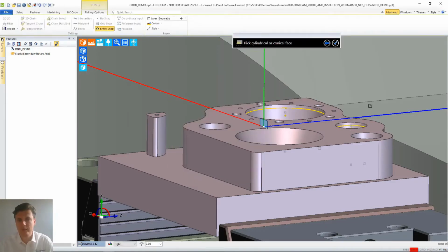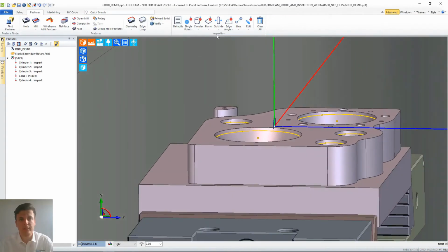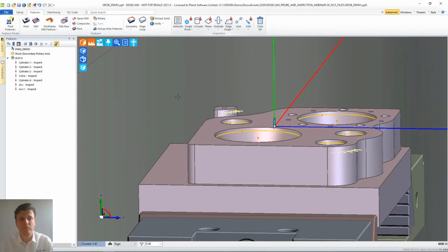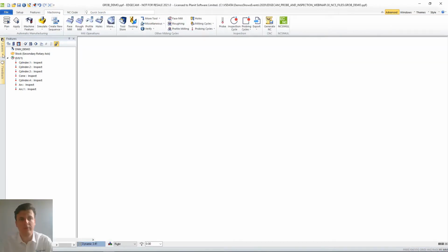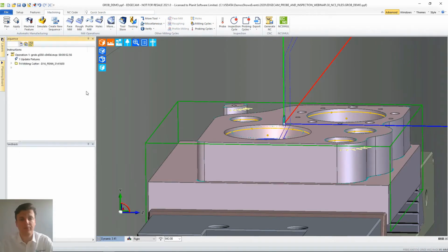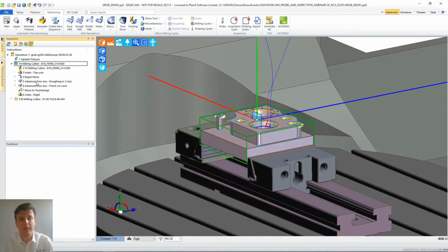Now you can see on the screen there are 3 touch points appearing. Good, and then do an arc feature again. Keep it with 6 touches. And then what we have on this prepared geometry: I copied the stock from the previous Doosan model. I created a roughing and a finishing 5-axis toolpath, and I selected the shape probe.